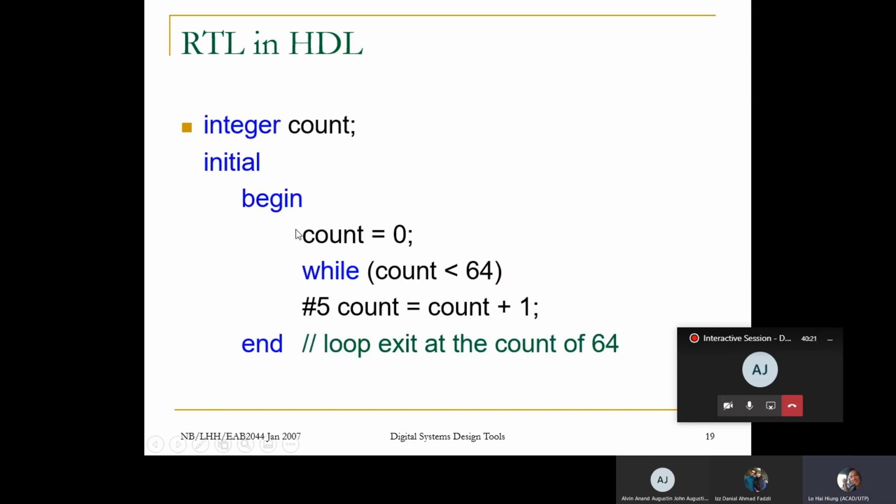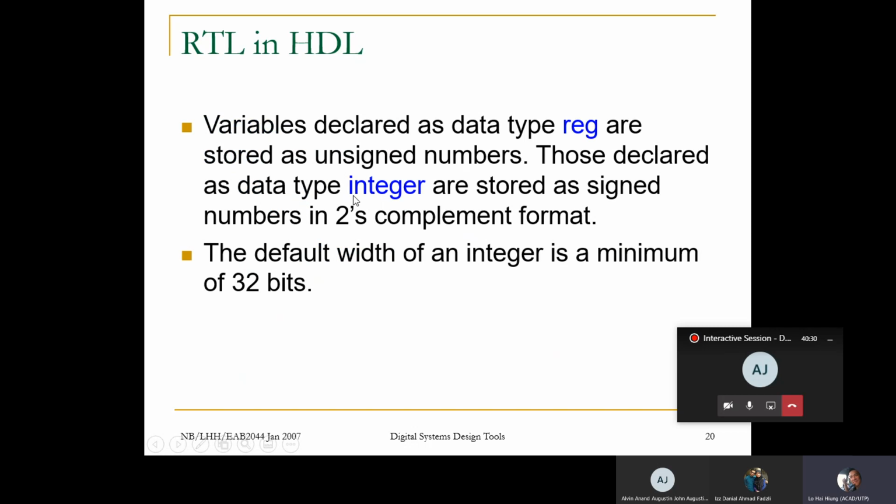All right. In here, you can declare integer type in Verilog. It recognizes it. By default, integer is 32 bits. We normally don't use this in hardware design. It is normally used in the test bench. The reason being is it is not describing a hardware. Integer is a software concept. So we typically don't use it in hardware design. So avoid using integer in hardware design, but you can use it in your test bench. If you want a quick and easy variable, you can use it.